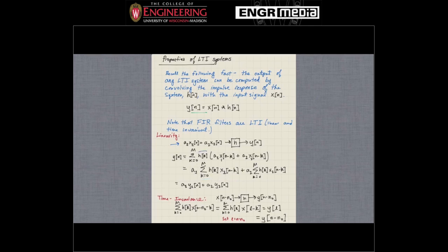Remember, we're taking this sum. We had b_k written before, so this h of k, we showed that was the same as the b_k, so we're putting h of k there. And that's getting convolved with the sum of two input signals. And then if you methodically go through this, you show that the output is exactly the same as if we had just input the signals individually and then added them up after the fact.